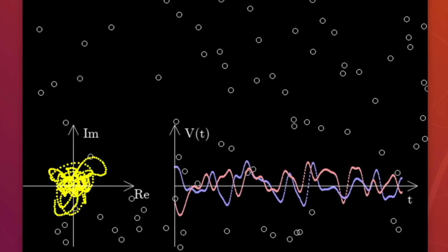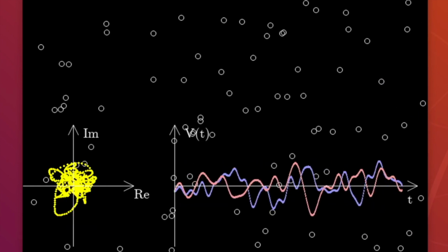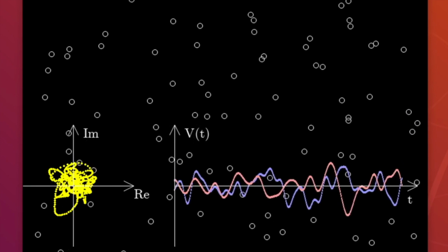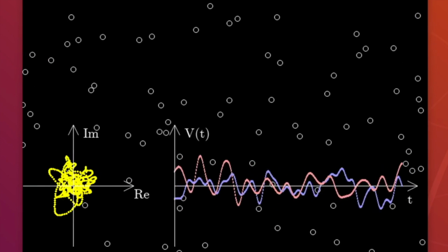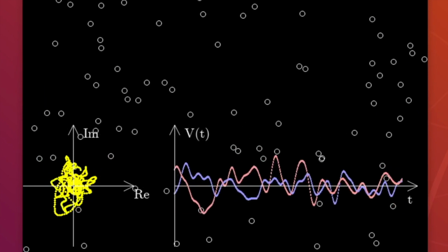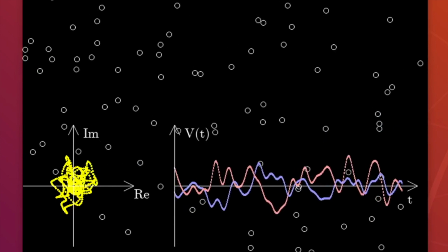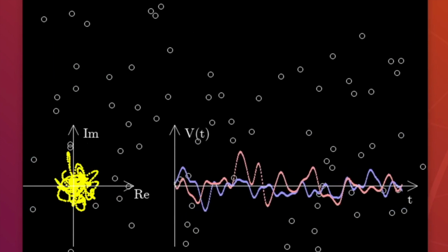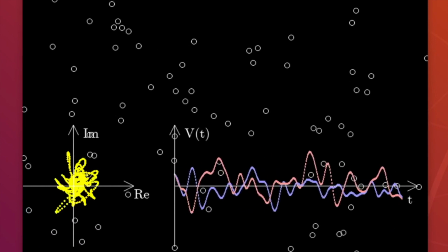Here is a simulation of an incoherent scatter complex voltage radar echo. In this simulation, I have placed electrons inside a volume at random initial positions. I have randomized the velocity vectors using a Maxwellian distribution. The Maxwellian distribution in this case corresponds to a normal distribution. The complex voltage, including the sum of all scattering contributions, is shown on the plot in the lower right.